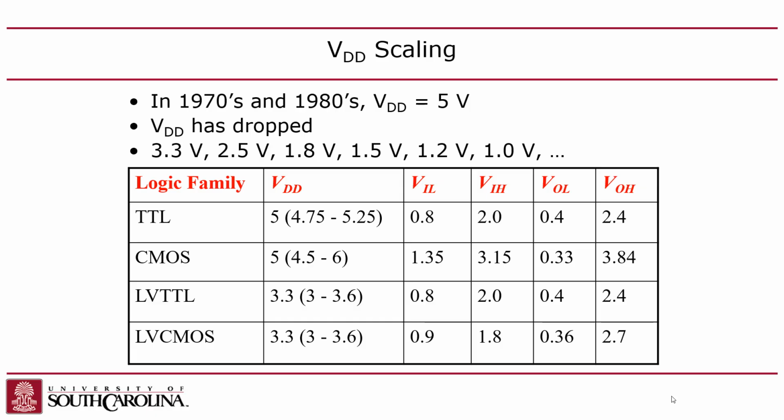And then for these different logic families, you'll have different VIL and VIH, right? So for low voltage CMOS, which is 3.3 volts, like what you'd have with an Arduino, VIL is about 0.9. That seems kind of high, actually.